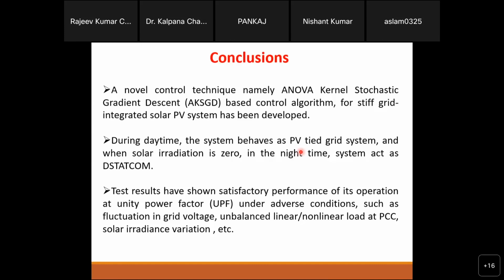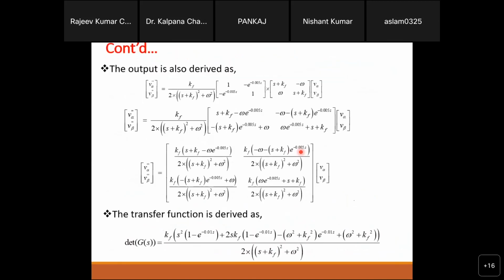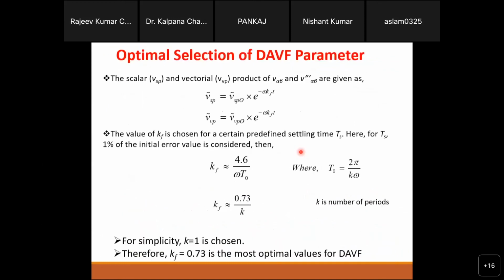and after that the two converters, and then the second converter output terminal you will attach on the PCC. Sorry, not PCC, I mean the DC link. That's it. And all the rest of the control behaviors will be the same, nothing else. So you can use it for that purpose also.